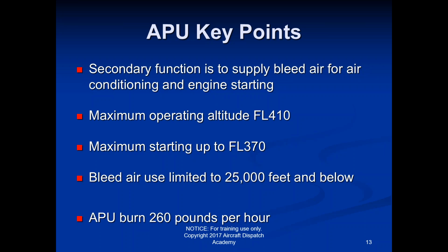so the APU, if you can think about it this way, the APU is like a little mini jet engine, okay? It has an air intake. It functions the exact same way a jet engine functions. It's just a really tiny one. We don't obviously use it for any engine power per se, but engines in general, whether it be your car or a jet engine, provide electrical power. And in the case of jet engines, they suck in air and combust that air, and that all creates your thrust, and that turning of the engine creates electrical power.